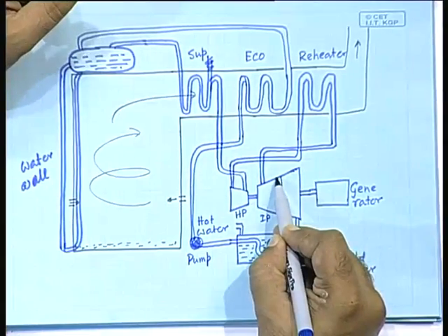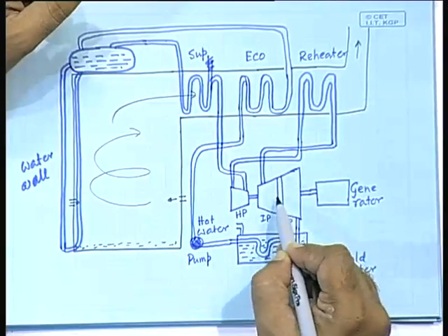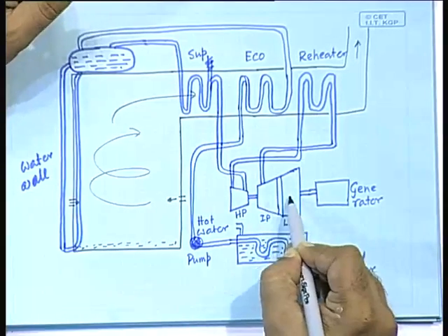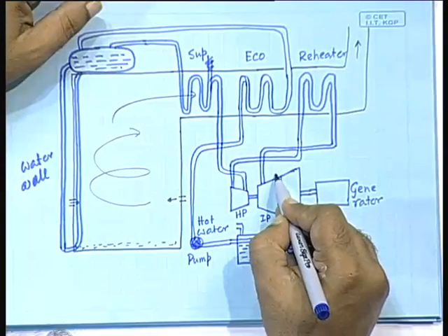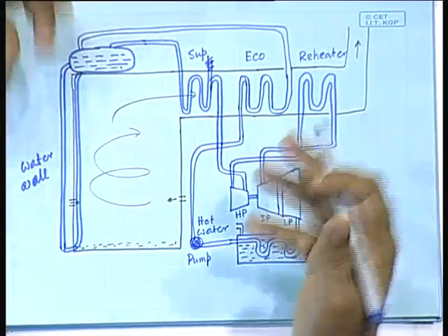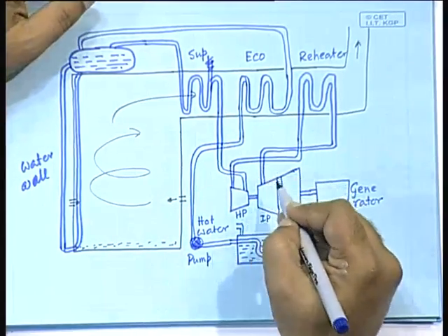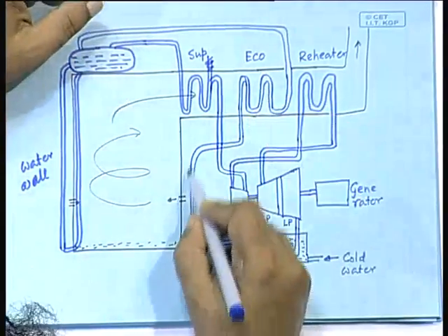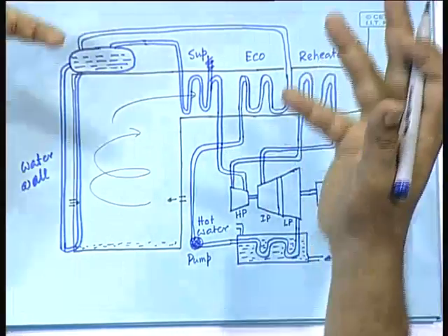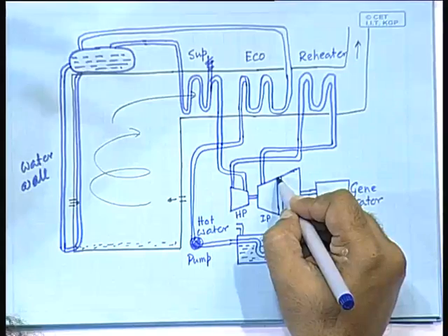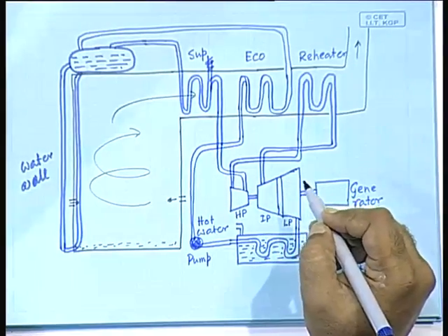That is done by taking a part of the steam out from in between the intermediate pressure and the low pressure stage. They are still hot. So, a part of the steam is bled out, it is like bleeding, part of the steam is taken out, and that is mixed with this water, so that the water goes to a higher temperature. Okay. So, this process is called regeneration.